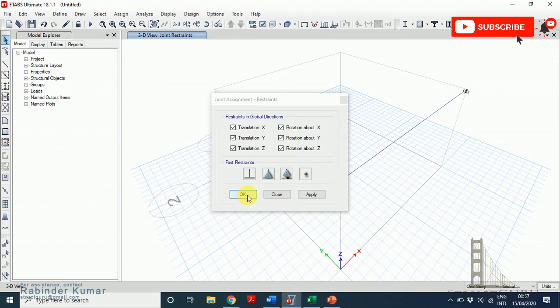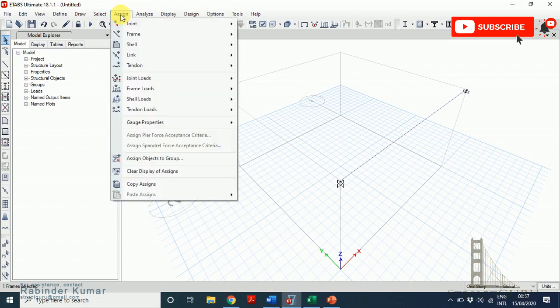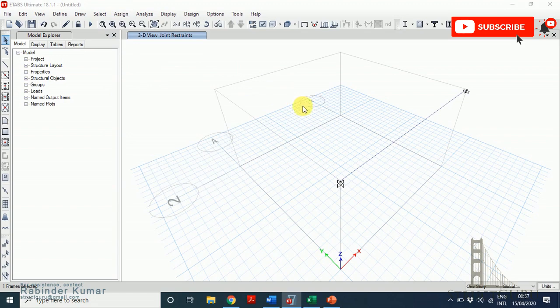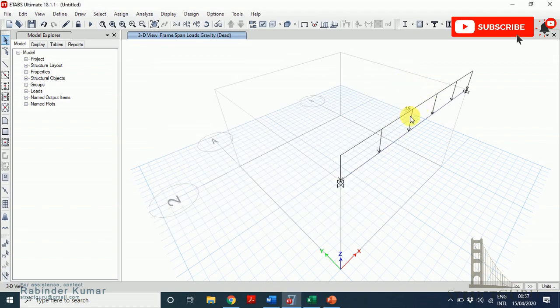As we have drawn the beam, we have to assign a load. Select the beam, go to the assign menu, go to frame loads, distributed. As I told you, I am assuming 15 kN per meter of uniformly distributed load throughout this beam. So click OK. The load is assigned.